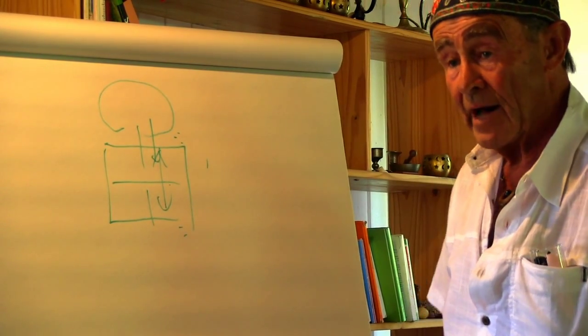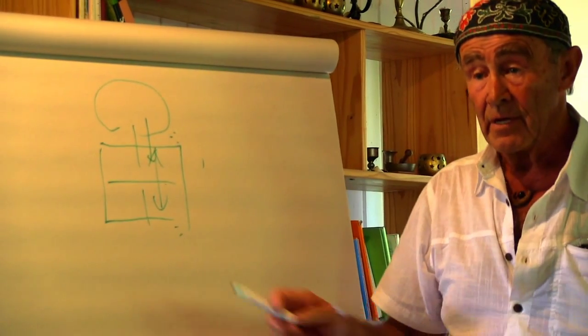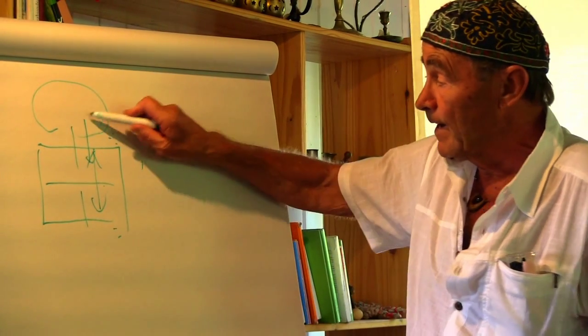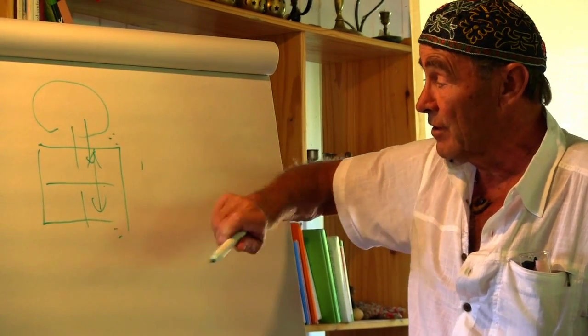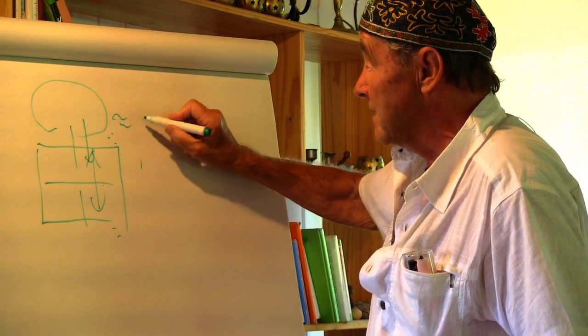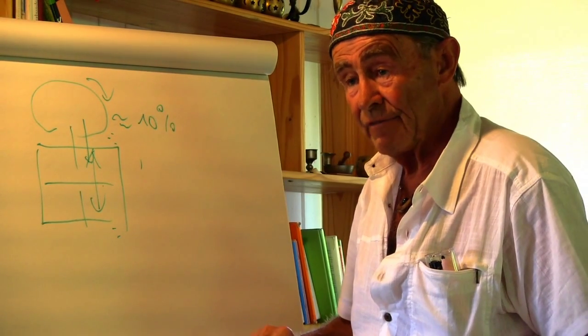To give you this in numbers, one of the reasons why we have slow motion engines, in the range of 1 to 5 hertz, as I told you, is that the displacement energy for the air is about maximum 10% of the energy lying in the flywheel.